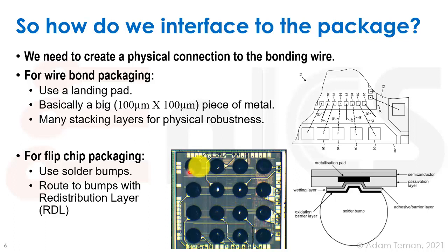And again, we put this passivation opening on top of this top metal, this RDL layer, and then afterwards the package house will connect these solder bumps for you. So you'll get this thing with an array of 16 solder bumps on it, which you then flip, and you'll have an array of 16 landing areas on the package itself, and we'll heat it up and it will connect.